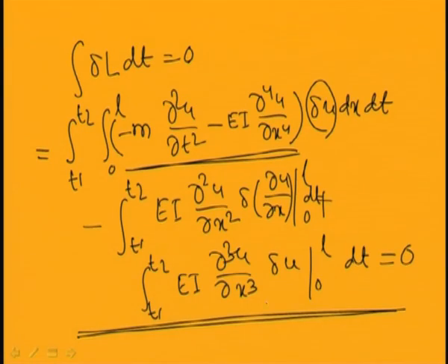So, here we have derived the Euler-Bernoulli equation by applying this Hamilton principle. Along with this, as we have taken the beam to be of general type, we can find all possible boundary conditions also. So, from these two expressions you can find the boundary conditions. So, for this general case we have found the equation of motion by applying this Hamilton principle. So, in this case we have seen that by applying Hamilton principle you can get the equation of motion and the boundary conditions.